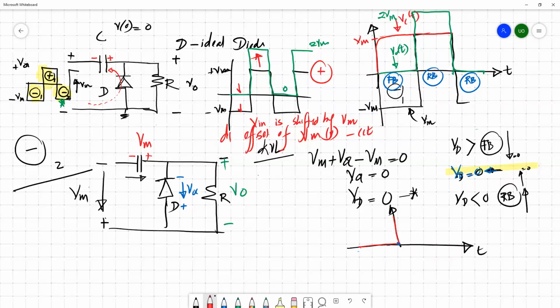Initially your input is a bipolar signal. So you have positives and negatives, symmetric around the t-axis. But once you introduce this capacitor and a reasonably high resistor to make this time constant pretty high, you can have a circuit which provides an output that clamps your input at Vm. You have a positive voltage which basically varies in the positive domain only.